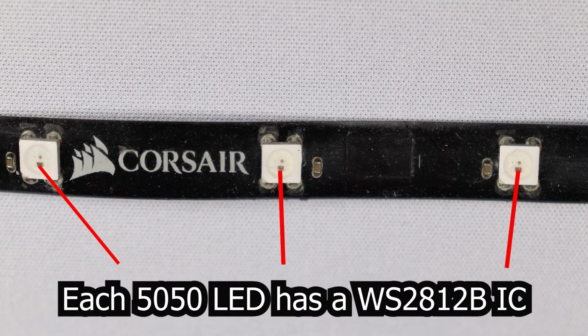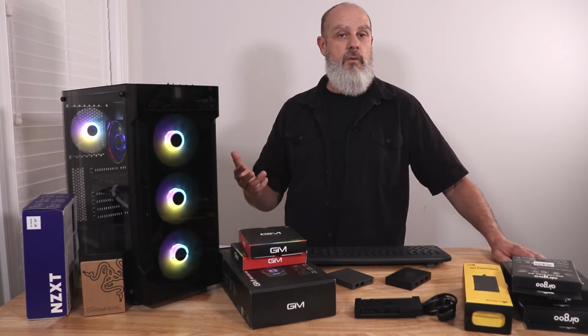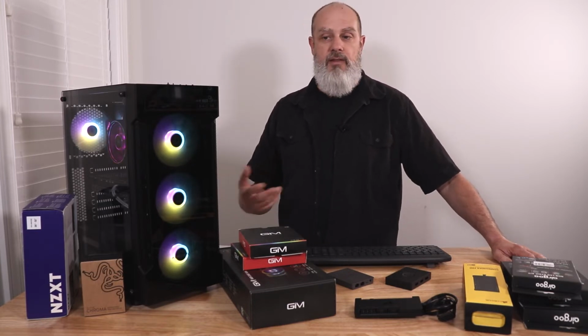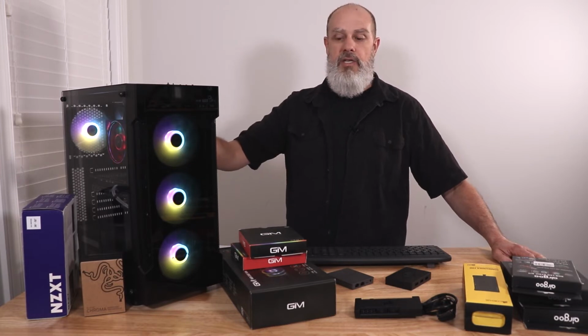Well, that's a 5 volt chip, and that's kind of how you communicate with it. So you don't want to throw 12 volts to it. Now, if you start Googling this, there are WS controllers out there that will do addressable RGB on 12 volt signals. But as I delve into some Christmas lighting and things like that, that's really the area where I see that type of stuff, not in the PC world.